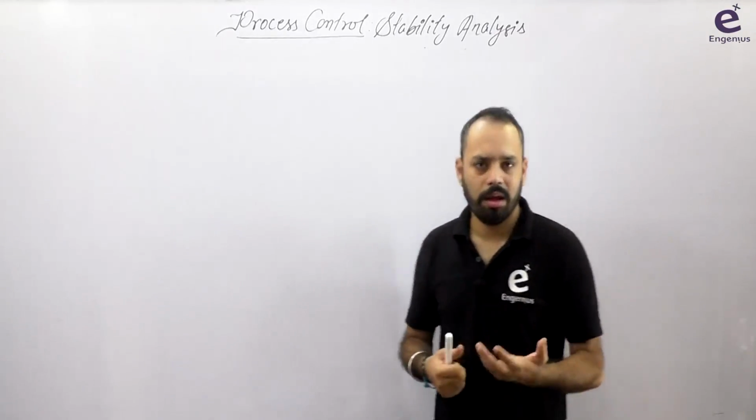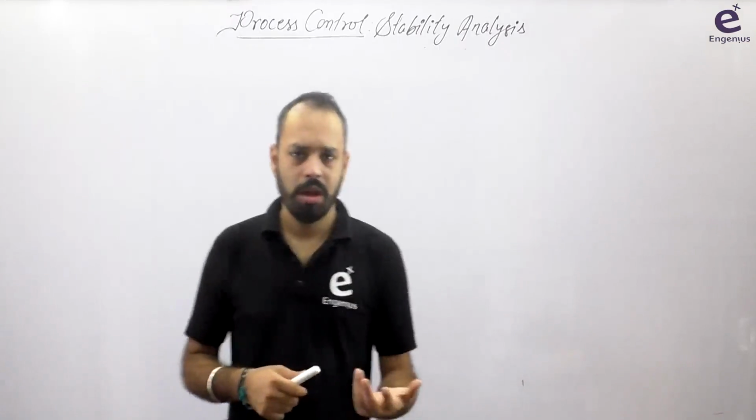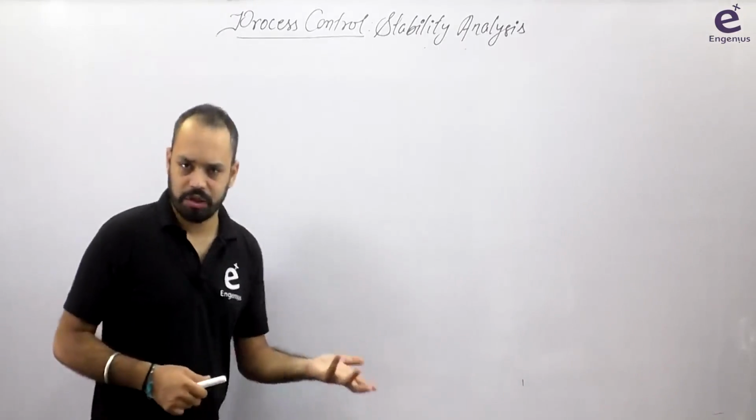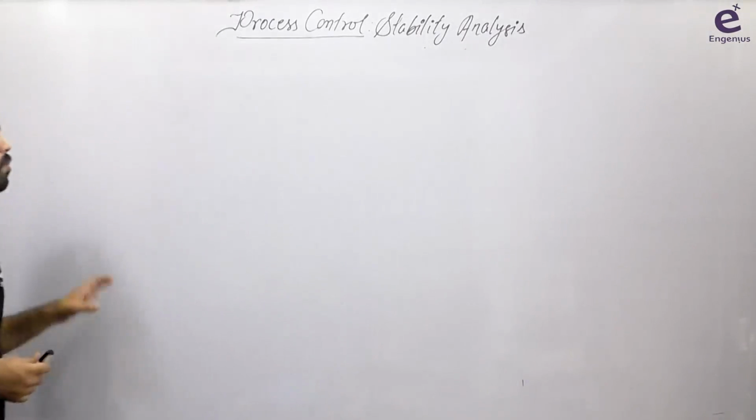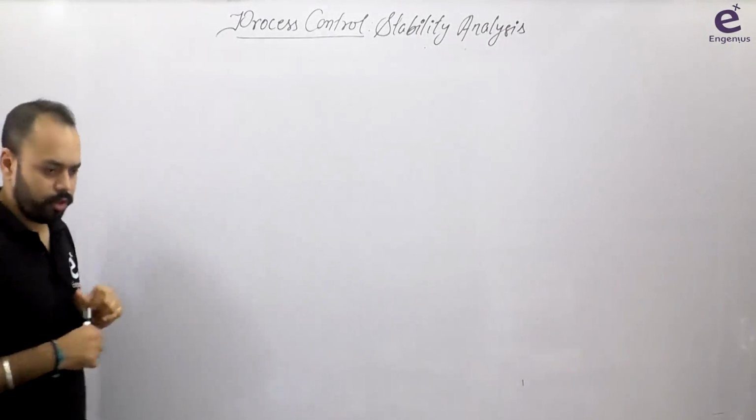Because for the second Bode plot, you know what happens with the phi. When the transfer functions are multiplied, the argument phi is added. So it's not possible to plot the exact nature here on this board. That's why I did only the plotting of the first Bode plot for the overall transfer function.